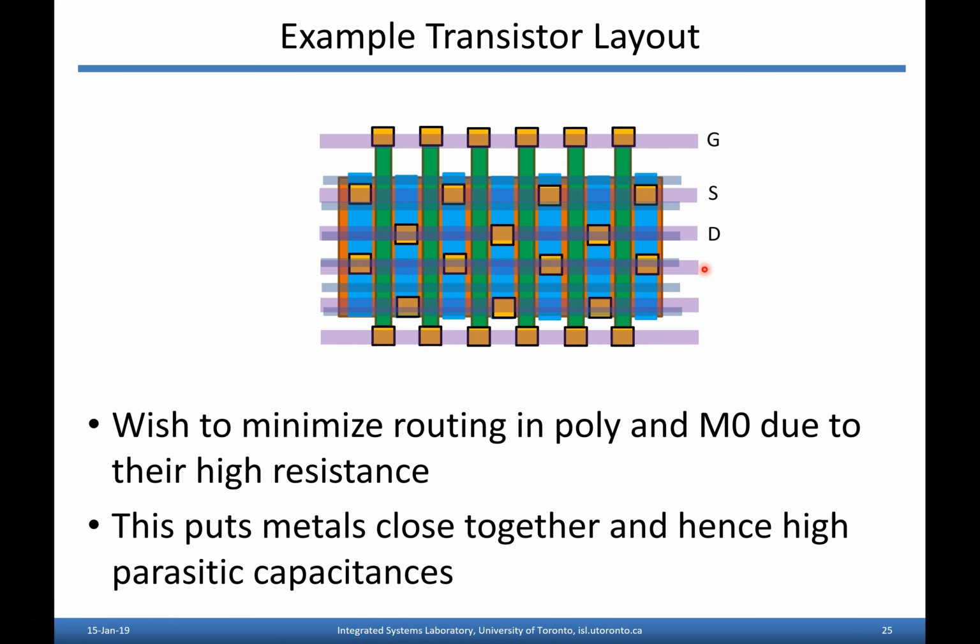You can imagine there's lots of CDS, capacitance between drain and source, because you've got all these wires running right next to each other to pick up the contacts. And then you've got to run the gates out in this layout, this particular layout style. There's other possibilities, but here you've got to run the gates out far enough to be able to contact to them without violating design rules, right? So these vias, there's obviously going to be minimum spacing requirements here to these vias, so the gates maybe have to run out a little bit further, and that adds a bit extra series resistance.